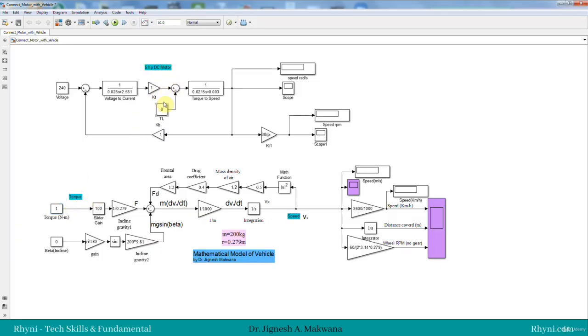This will not have the feedback effect, because the motor rotor inertia will remain the inertia of only the shaft, which is very low. So this shaft and rotor will certainly reach a high speed, and this torque will act only as a measurement quantity supplied to the vehicle model. The vehicle model will give output according to this measured torque, but it will not give the actual speed of the vehicle and the motor on varying the supply. So this is one thing.